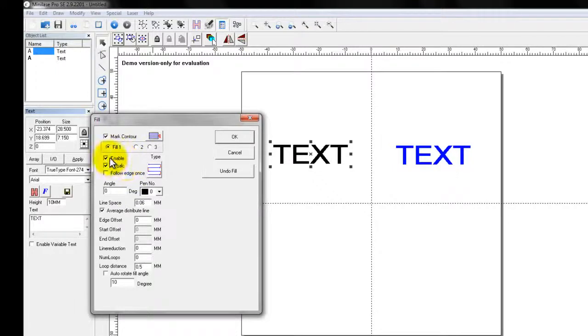And so what that means is if we wanted to, let's say, do a deep engrave on a material, I would use one pin for my first fill, and that pin would be programmed over here for deep engraving, and I would likewise set up my fill. And let's say after the deep engraving cycle is done, on the next pass I want to come in and clean it up a little bit, polish the bottom, get some of the burn out of there. What I can do then is set a separate pin. Let's say that's our red pin, pin 2.